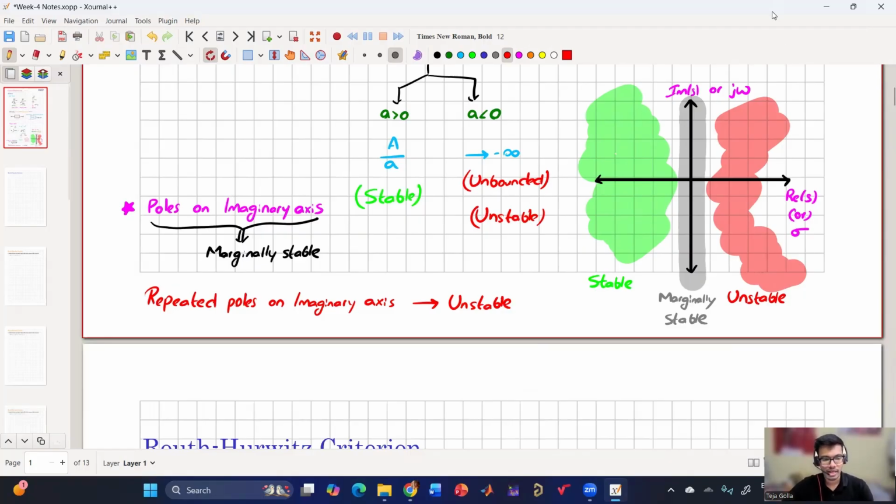So now we can understand if we are going into S domain and if we are checking the stability of the system, the objective is to find the pole location. So if it's a first order or second order, we can find the pole location. But say if the order has increased to sixth order or fifth order, how do we know the pole location? We don't have to calculate whether the pole is at -5 or -10, but we just have to ensure that pole is not on the RHP side. So we have to check whether the pole is on the left side, LHP or RHP.